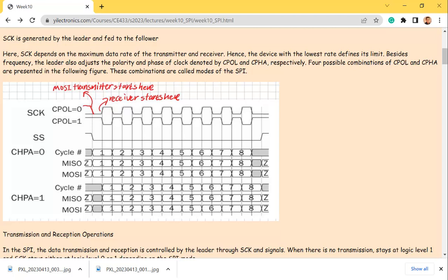The photodiode has photocurrent being sent to that chip, and the chip senses the current and converts it to voltage. Which means you need a TIA, transimpedance amplifier, op-amps. It's an inverting amplifier, but it converts everything to voltage. And the voltage is analog, so I have to digitize it, right? I got a digital signal. You digitize it. If it's an 8-bit ADC, we get 8-bit digital data stored in the memory.